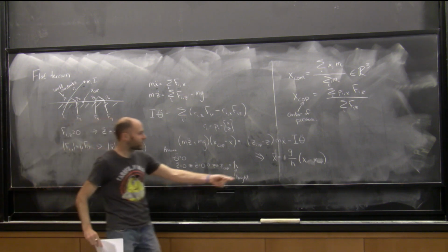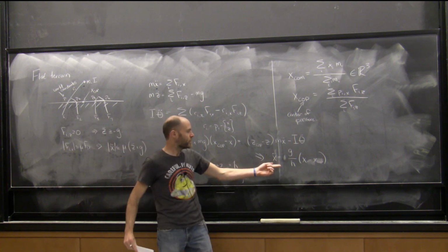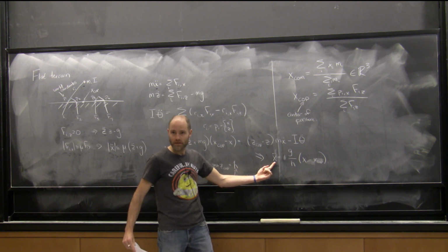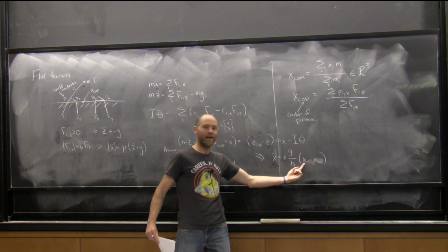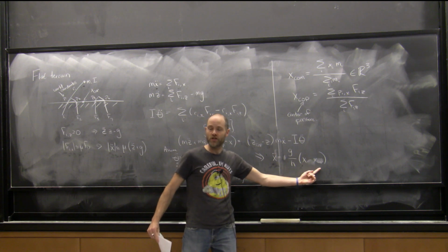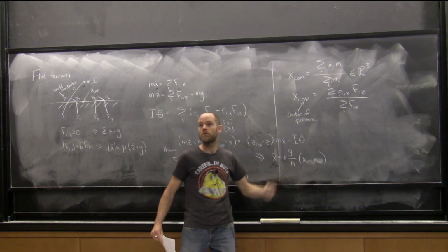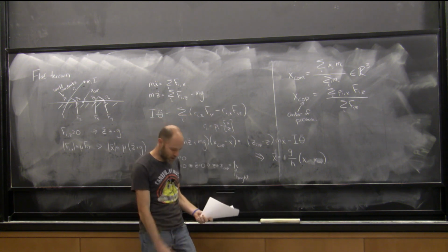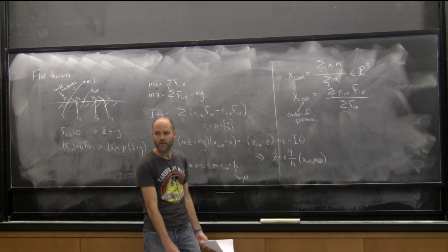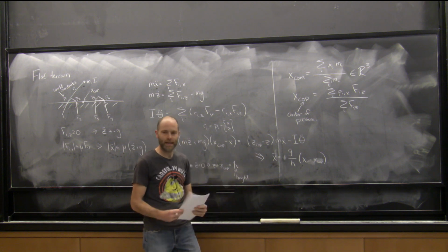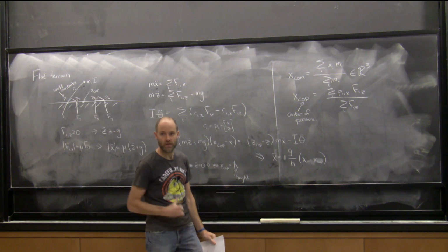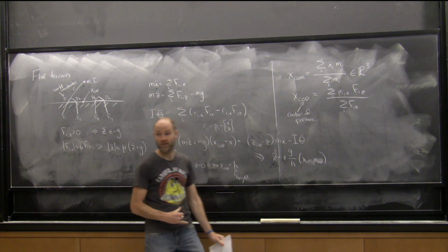Okay, read this off to me though, right? So this says the acceleration of my center of mass is completely determined by the location of my center of mass relative to the location of my center of pressure. Okay? So my center of pressure, the forces I'm exerting on the ground, and my center of mass, their dynamics are completely linked. If I know where my center of pressure is and my center of mass is, I know how my center of mass is accelerating.